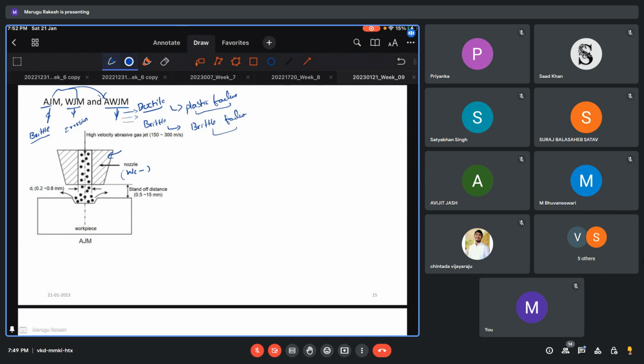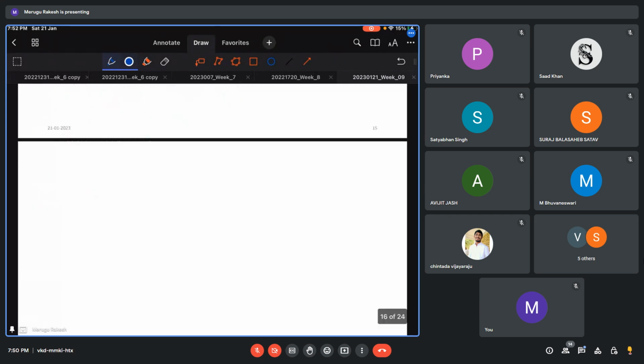In water jet machining, we use intensifiers, in which we get very high pressurized water, which is allowed through nozzles. So this high pressurized water, when it hits the surface, will slowly erode the surface and pass through. In abrasive jet machining, we are just combining these two effects. Okay, this is the basic principle. I will talk more later.